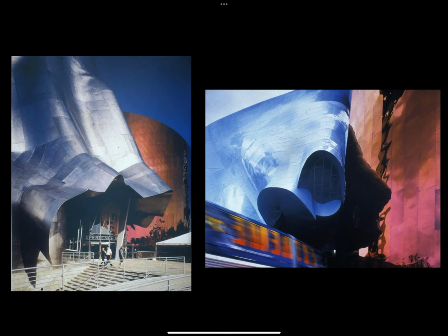Regarding fire resistance, no metal cladding system has any fire resistance. So this is different from, say, concrete cladding or brick cladding. If we're using concrete or brick, it enhances the fire protection of the external envelope. If an external envelope with metal cladding needs to be fire rated, that has to be achieved in the backup layer because the metal doesn't contribute at all in this regard.